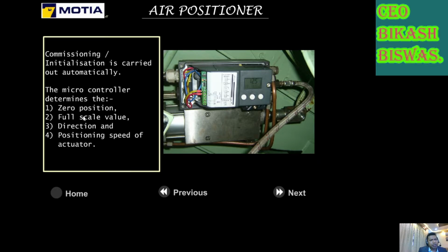So what is the zero position? Like the microcontroller, it will ask what is the zero position, what is the full scale value, what is the direction and positioning speed of the actuator.